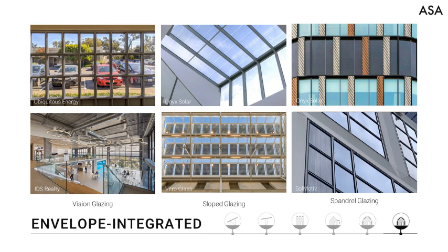Slope glazing offers the highest energy generating potential of the category and presents an opportunity to filter light in innovative ways. Crystalline technologies can be utilized similar to a frit pattern on glass, and thin film technologies can tune the visible light transmittance of glass by altering the thickness of their coating. Generally speaking, the more opaque a coating, the higher the efficiency. Spandrel glazing offers the best opportunity for high efficiency technologies because it is typically opaque. Its purpose is to span floor partitions or columns or wall partitions that are to be concealed from the exterior. High efficiency opaque technologies are great for these applications.